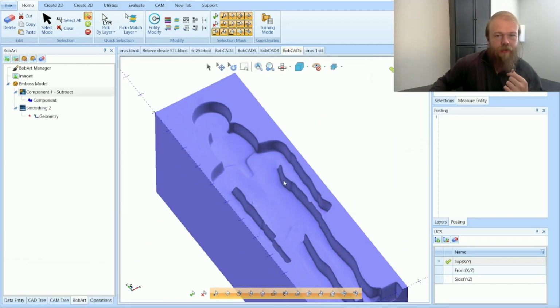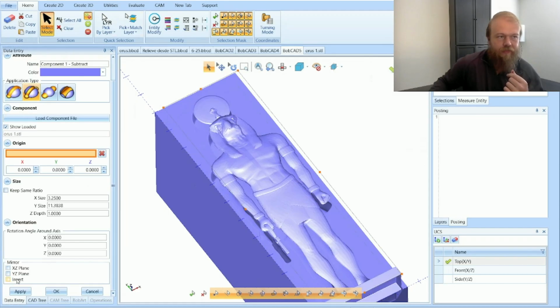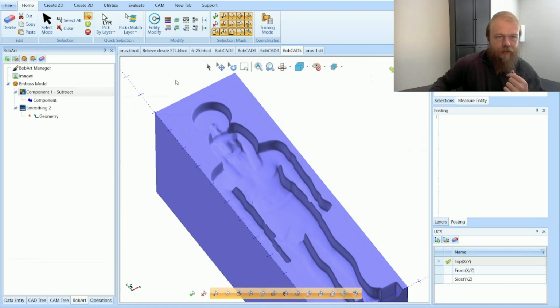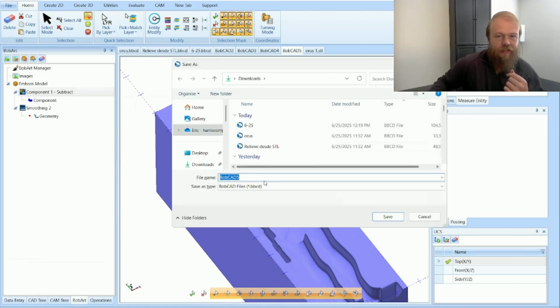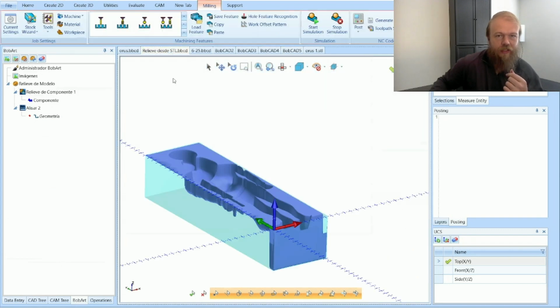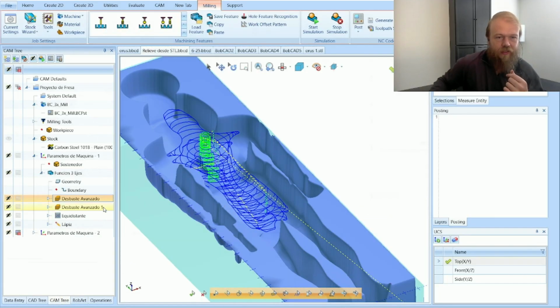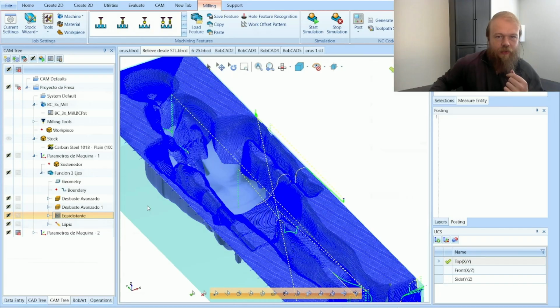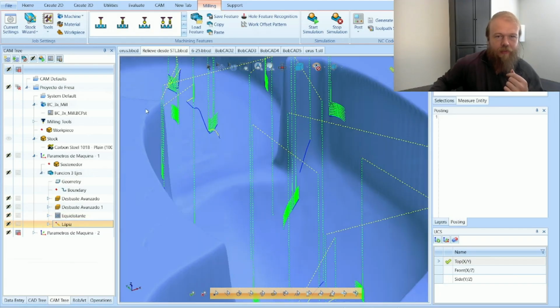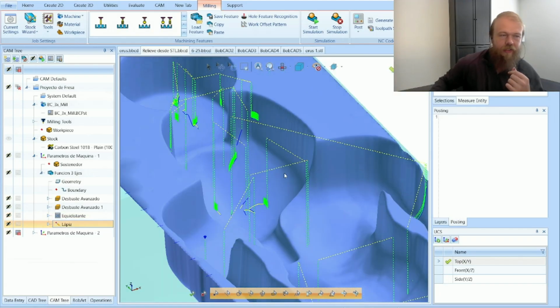So you've got your one STL file there. You could hit save as and save as, the back side. Come back, turn off invert, and click OK. And then save this as top side, and you've got both of your files that you can create a 3-axis roughing, an equidistant toolpath, and then a pencil mill to follow along all of the curves in here with the correct ball end mill that'll fit in there. A lot of good stuff there.